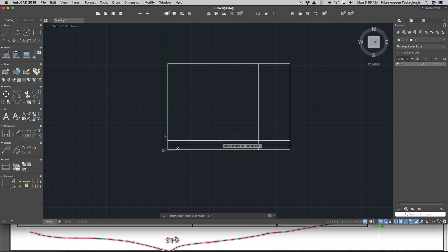How do you do it? The first thing you need to do is have your edge. Sometimes I call it your knife. Okay, this is your knife. Once you select your knife, you press enter. The first line that you select in the trim command is your edge, or your knife, that you use to cut the extra line. Then I press enter.